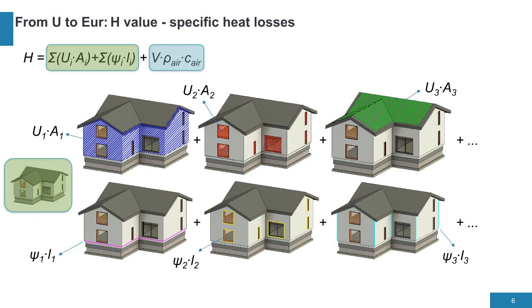A thermal bridge is a longitudinal element identified as the line where a floor meets a wall meets a window, in corners, and so on. The thermal characteristic of a thermal bridge is described by the psi value, which indicates whether we need to increase or decrease the calculated heat losses. Most psi values of thermal bridges are positive, meaning we add a small amount to the heat loss calculation. This share of heat loss might be very small, up to a few percent, for energy-efficient buildings but can be significant for older buildings, consisting of 20 to 30% of the total heat losses.